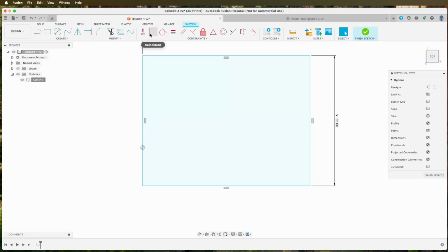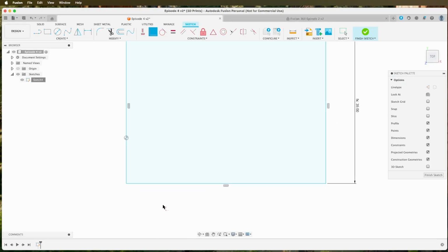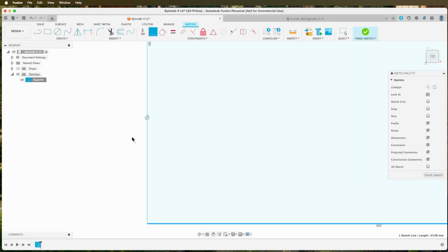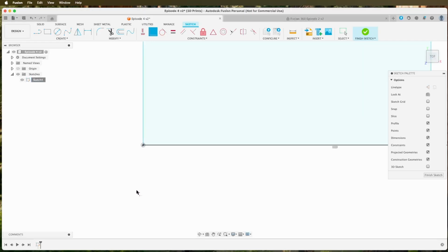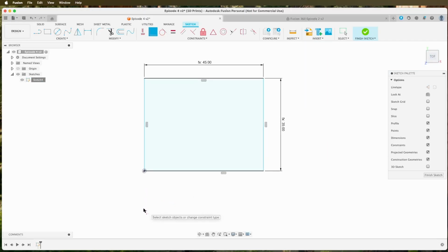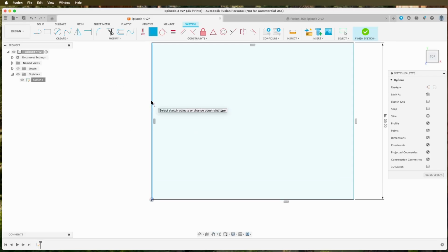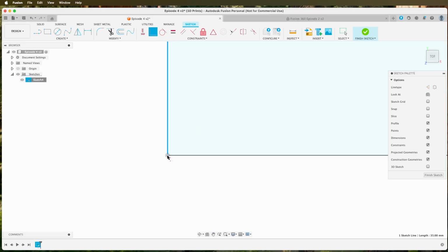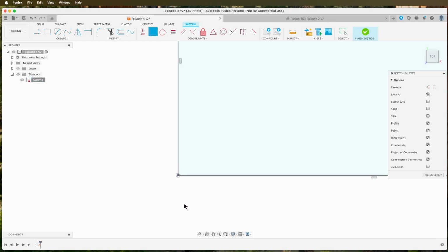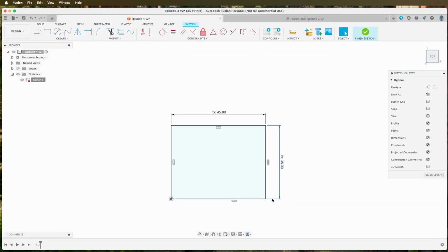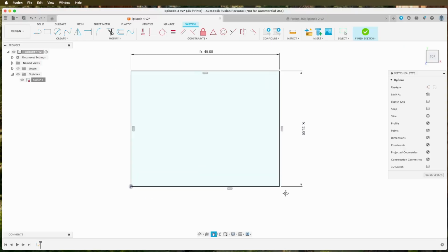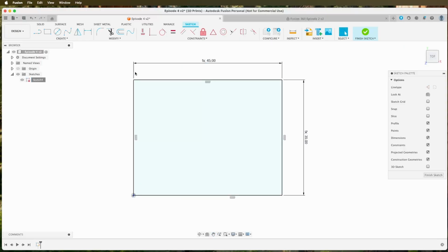to go here and say coincident. So if I do the coincident and I say I want this line to be coincident to that point, you'll see everything has moved there. And while we are here, I want to make this line also, was already, but coincident to that point. And now, if you have noticed from the previous windows, all these lines are now black. They are not blue anymore. That means all these lines have a constraint.